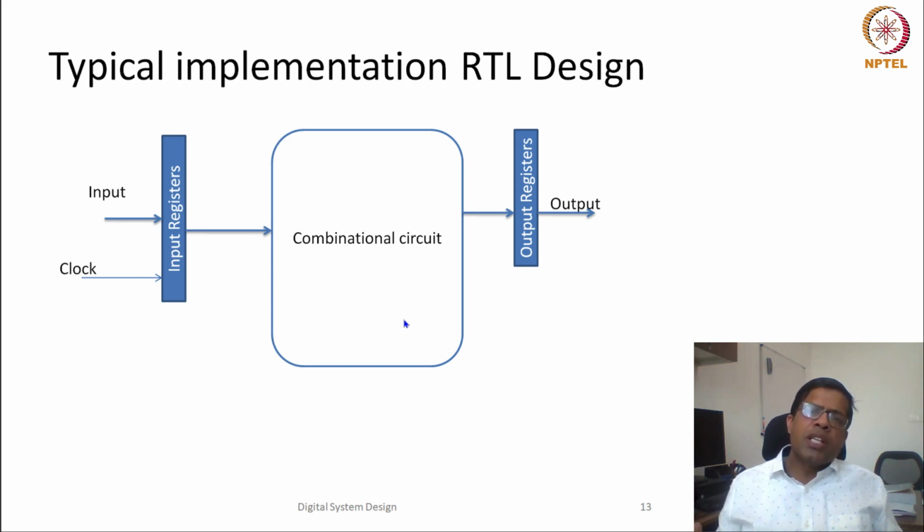So in this overall implementation, input is read from registers and output is written to registers, but there would be a state machine which manages the operations and decides which operation is to be performed in which particular cycle. We have already discussed these state machines in our previous modules as well as the current module. These state machines consist of certain registers, which we can call state registers.